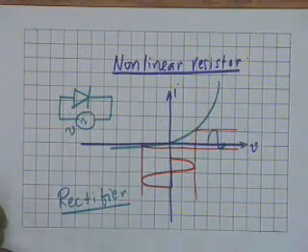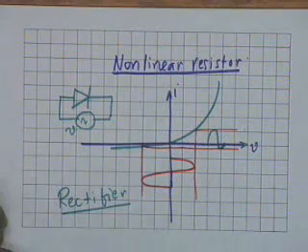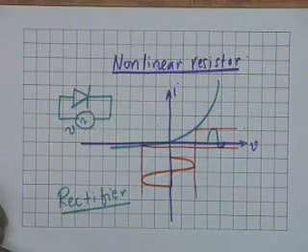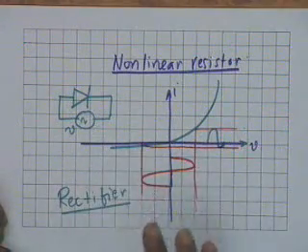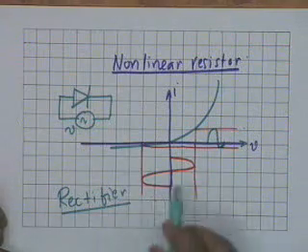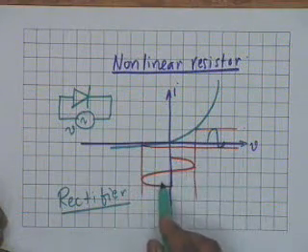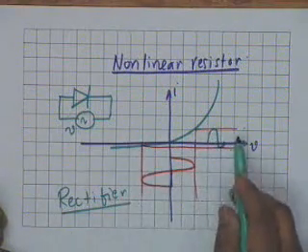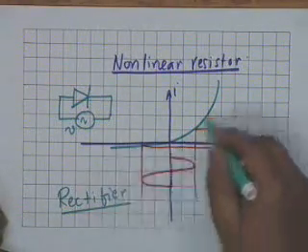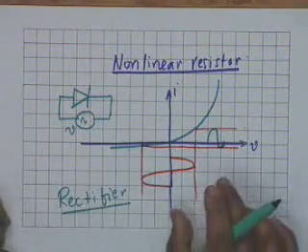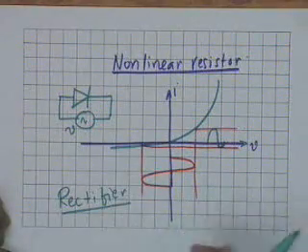We shall take a fairly complicated example a little later of a circuit containing nonlinear resistors. But let's look at an analytical method. This is a graphical method. Is this graphical method understood? You look at the voltage variation. This is the voltage axis. So you look at the voltage variation, the corresponding current, you plot it, and you see this is what you wanted to find out, the current I. So if the characteristic is given graphically, then you can find out the output. Here the input is a voltage and the output is a current.